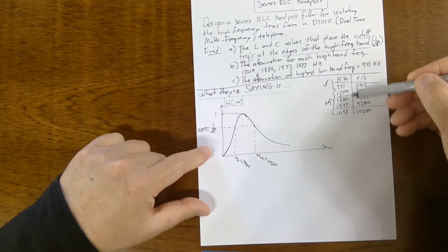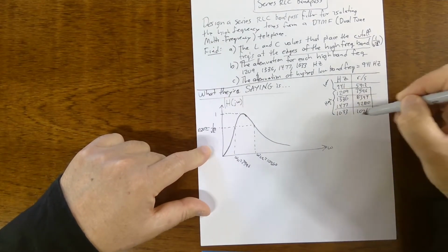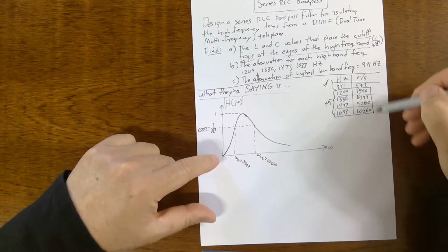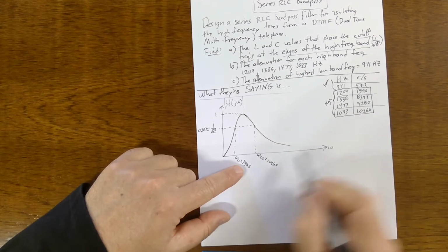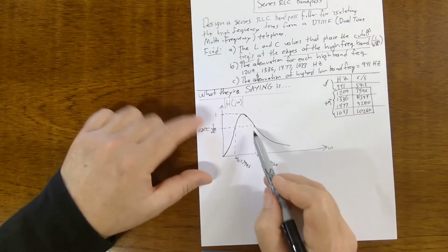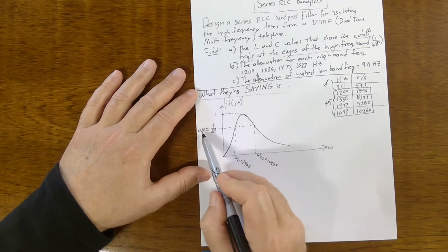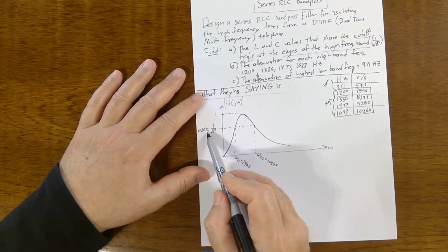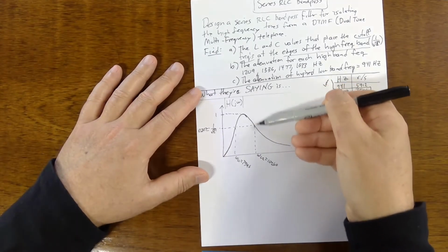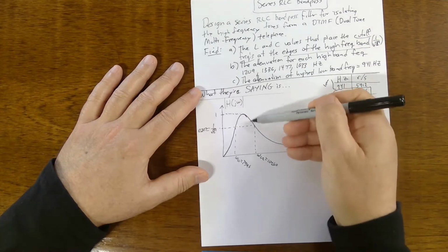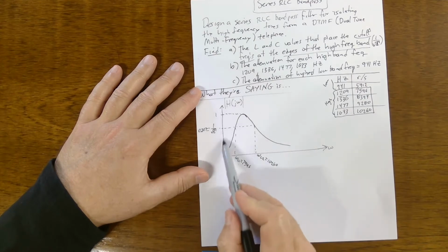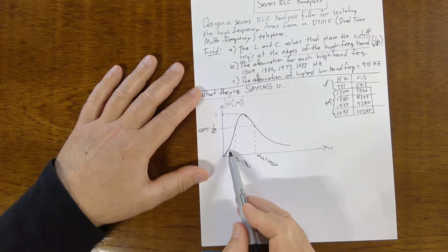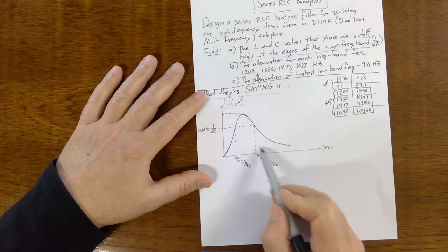So this whole high band between this band of frequencies, this range of frequencies, lowest to the highest, 7596 to 10260. These will make it through the filter because they will be attenuated no more than 0.707, which is considered acceptable. We say that these signals get through because they're attenuated no more than 0.707, and we say anything below that, any frequency down in here will be cut off, and anything up in here will be cut off.